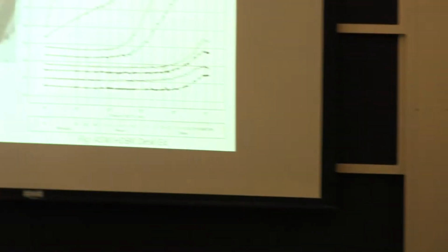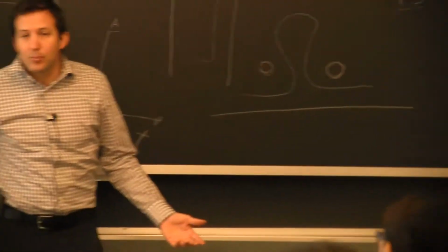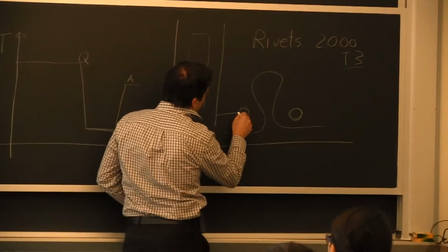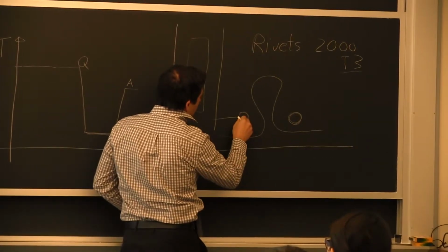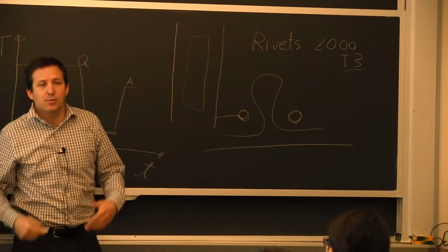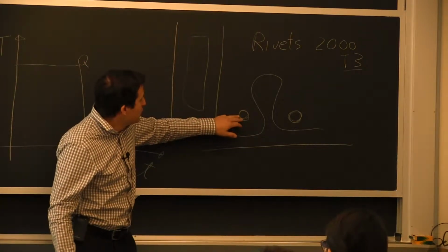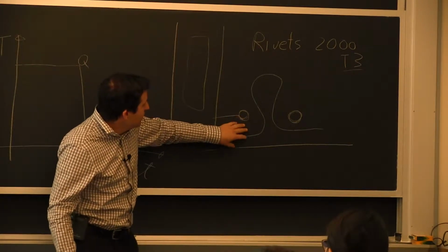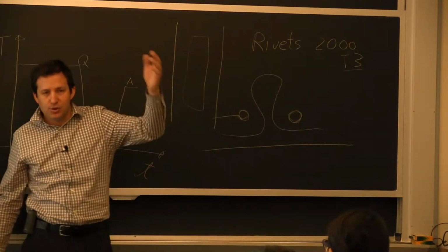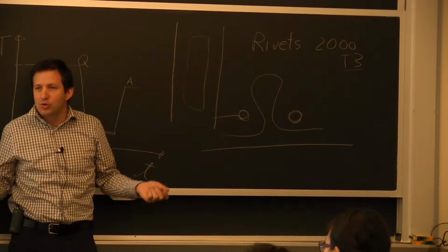When you see it's going down, it's because now these precipitates are becoming so big that the dislocation will just come around, and if you don't have a coherent interface, it will just jump around it. Right on that interface, it's a little bit like a grain boundary at that point. It doesn't have to fight and feel. It doesn't feel that there's a precipitate until it reaches it, and then it just goes over. So at that point, the precipitate is just too big.